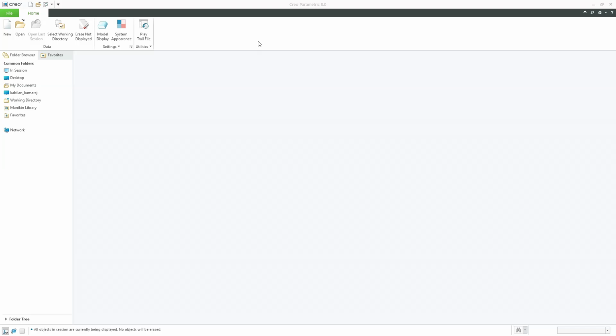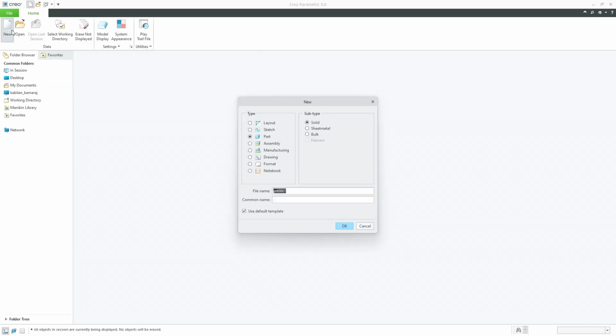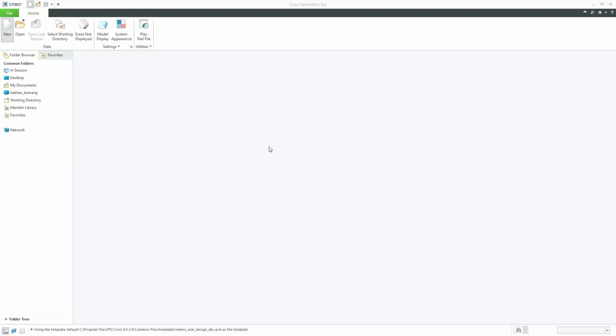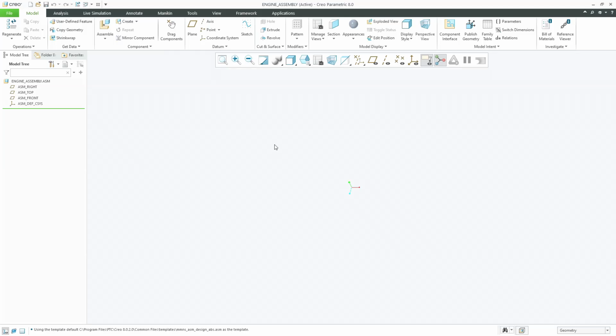In this mechanism we are going to use these parts, and finally we are going to assemble a gear at the output of the crankshaft as well. So let's get into the mechanism. First I'm going to create a new part, and for this I'm selecting the assembly workbench, renaming it as engine assembly. Just click enter here. So a new engine mechanism assembly workbench has been created.